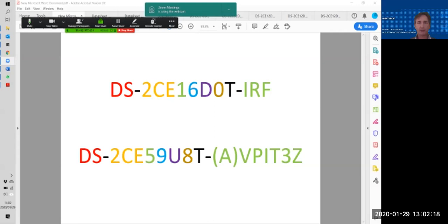The next letter, D or a U, identifies the resolution of the camera. You might have a C, D, or U, and D in this case means 2 megapixels and U means 8 megapixels or 4K. The last number over there, 013589, talks about the feature sets that are available in the camera. So nothing to do with the physical format of the camera, but more about how the camera is able to work with the images that it's busy capturing.